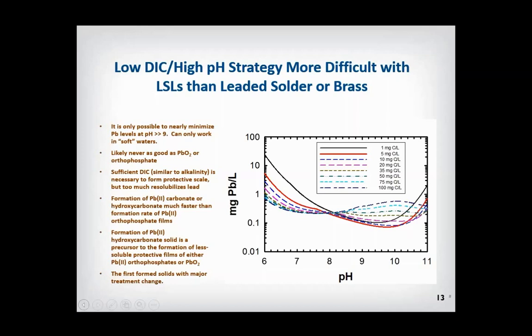And the carbonate solubility is also important because when you change background water chemistries, the fastest reactions are the carbonate reactions. So even if you're adding phosphate and trying to re-equilibrate to new conditions, what happens in the initial disturbance will affect the carbonate minerals. And so if you're trying to drop your pH from a high pH adjustment system to 7.5 to do orthophosphate treatment, the lead levels are going to go up dramatically for quite a period of time while you're doing the transition.